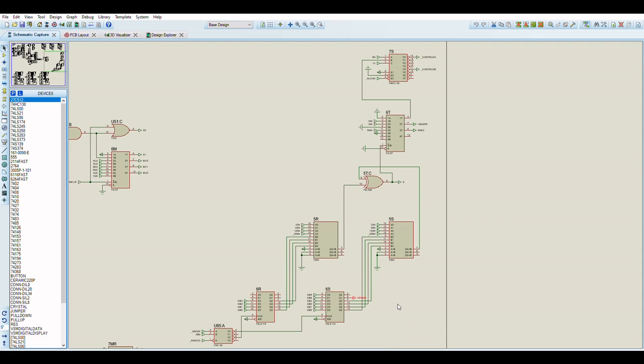There's also the Sprite enable or disable, so the hardware, by only setting 1 bit, can turn off the entire Sprite plane. This was added by me because I wanted a nice, quick and easy way of turning off all of the Sprite. The Sprite calculation still goes on, but the pixel output does not happen. There is no pixel test.